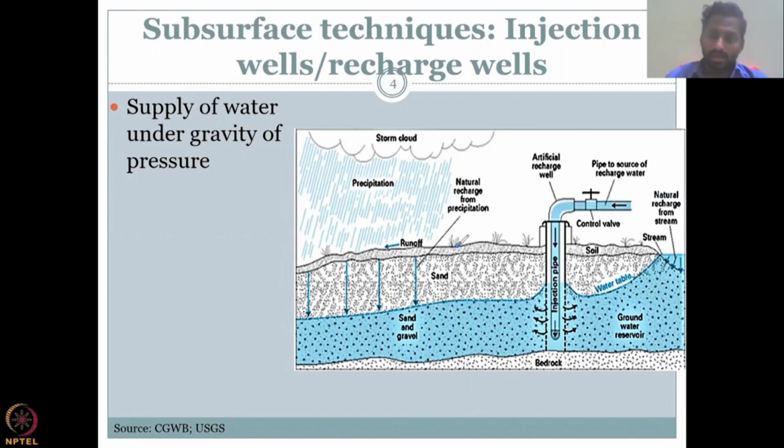So in the land, you just make a well. It's a very small well where only the injection pipe can go through. It's like a big pipe which goes through, and the pipe is connected to a motor where the motor pushes water inside the ground. And you only open along the pipe where you want to recharge.